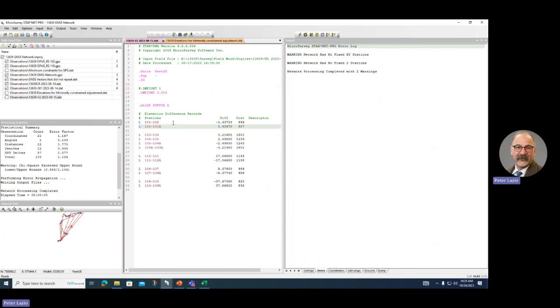So in order to take care of that, we talked about this yesterday, StarNet has what's called an alias. So you tell it dot alias suffix. Anytime it sees a suffix of A, it's just going to ignore that A, and so 101A is the same as 101. Those are probably the little tricks that Jolly wasn't using, because when he showed me this stuff, he was manually going through there and removing all the A's.